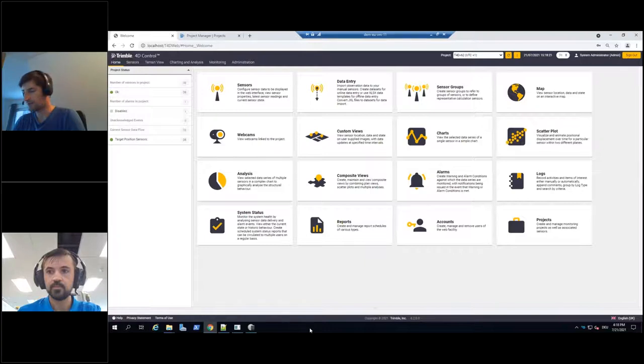So maybe first some explanation on my setup. I use a real alignment that has been used, or that is still being used, by the Grand Paris Metro project. You will also see it later on the maps page. I have configured about 40 positional sensors, prisms basically, that are close to the alignment and for which I get data on a regular basis. This is all configured already in T4D server, and therefore I will start in T4D web right away.